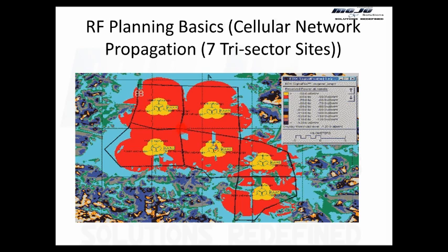So how do we differentiate between the signals? If you start to measure RSSI, then this is the addition of all the signals received from all these base stations. Maybe some of the signal from this base station is reaching over here as well. So RSSI cannot be the measure to make decisions if you want to camp on a cell. There should be a specific parameter which identifies the power from that particular cell, not the base station, the cell itself.